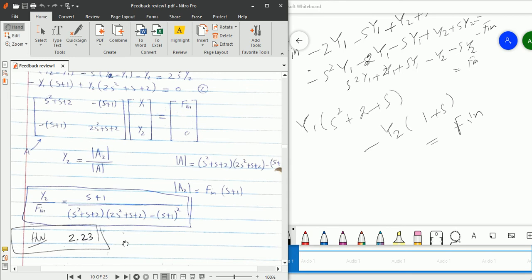You just need this equation. If you are able to get this equation, for example, if you want to further check the stability, you can further simplify it, make it equal to 0, apply the Routh-Hurwitz criterion. We will discuss it later in chapter 6, the stability chapter, and we will then be able to decide whether the system is stable or not.